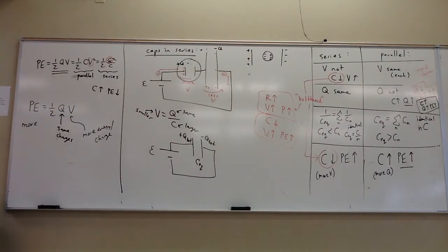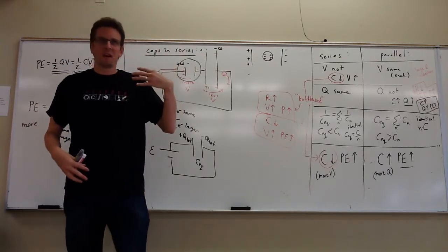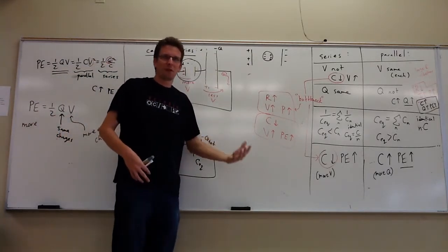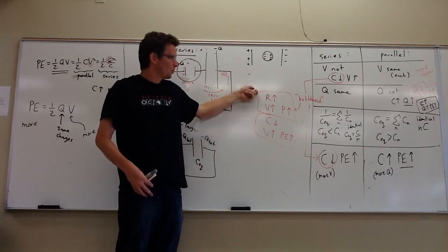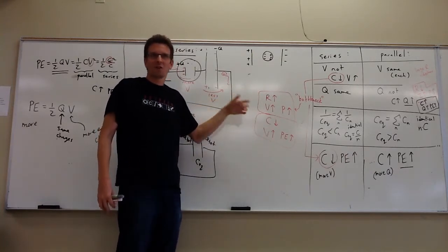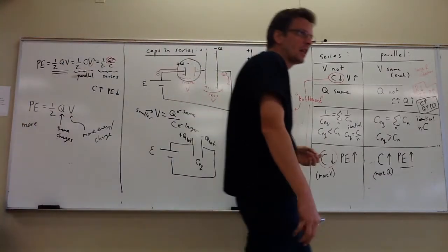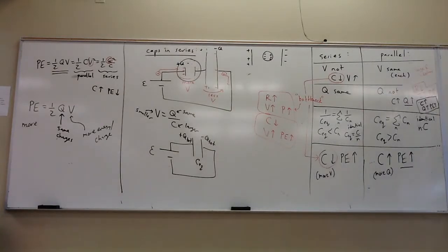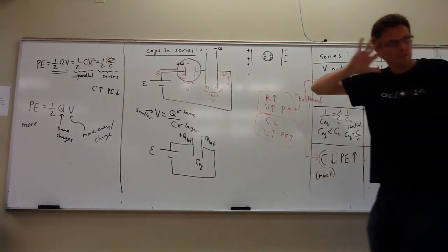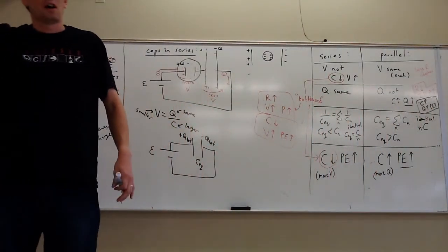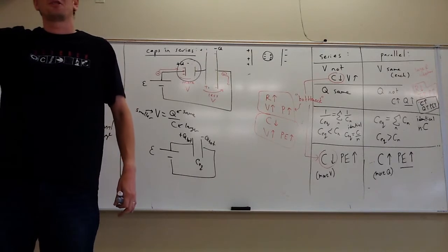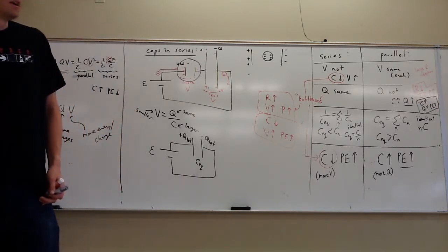So the common theme, right? The common theme is that when you're in series and you have to contend with everybody, the most action is the difficult, the bottlenecks, right? The larger resistors and the smaller capacitors are the difficult things. They get the most attention because you have to pay attention to everything. When you get to parallel and you have choices, then all the action's at the easiest way, right? The smaller resistors and the larger capacitors get the most action, and the difficult branches, the higher resistors and the lower capacitors, are the sideshow, okay?